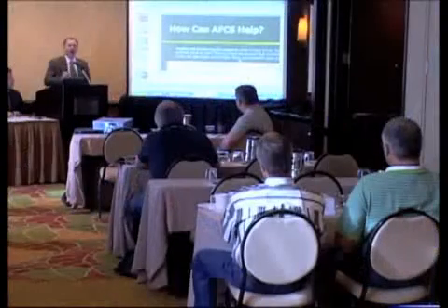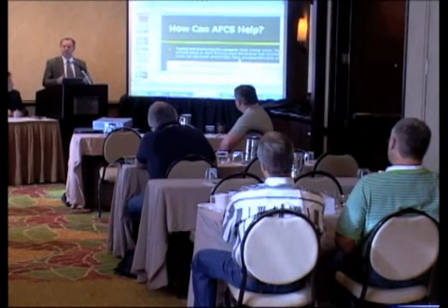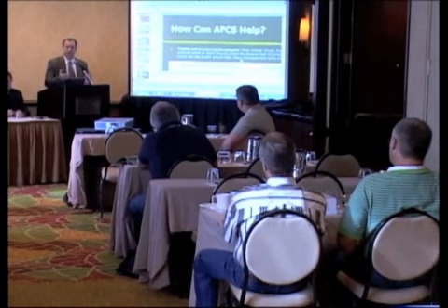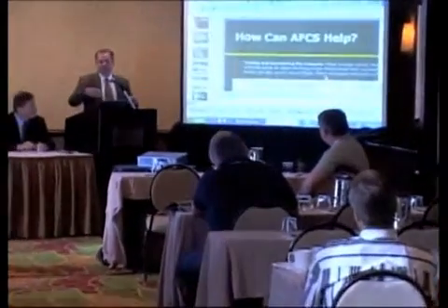Yes, yes. Yeah, the question is on active fiber, do we need to have a filter on the other end because you've got the 1625 signal going through your network? And the answer is yes. When you're doing active fiber, let's say you're running at 1550, you have a WDM, so your OTDR trace is muxed onto that active fiber, and then before it gets to the receiver, you put a filter which takes the 1625 signal off before it hits the receiver. And then that's your reference trace. And if anything happens in between those points, then you get your alarm and your location and so on. So the answer is yes.